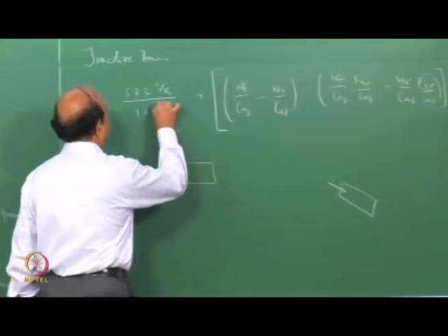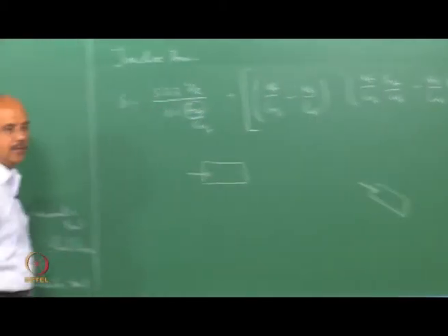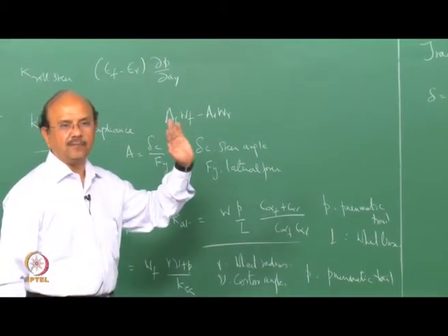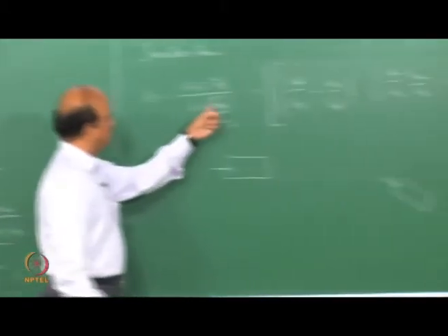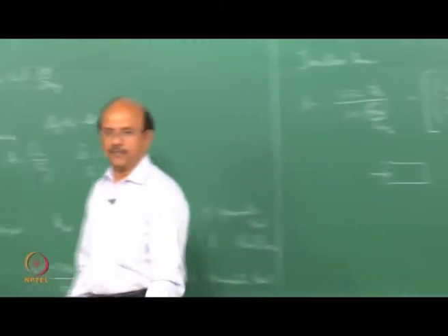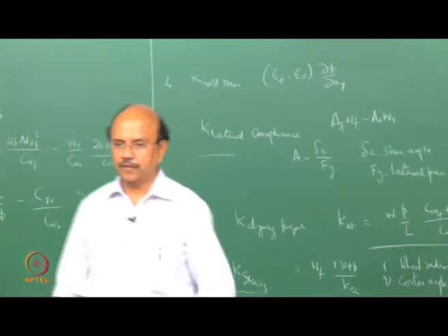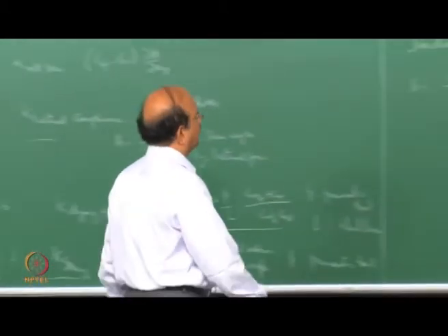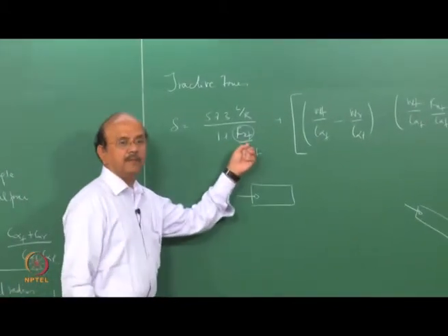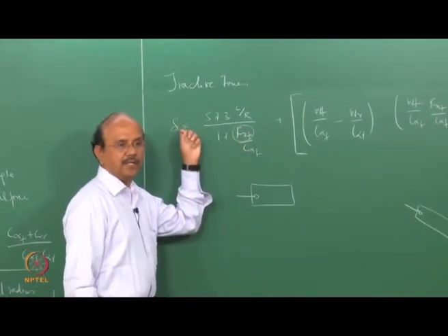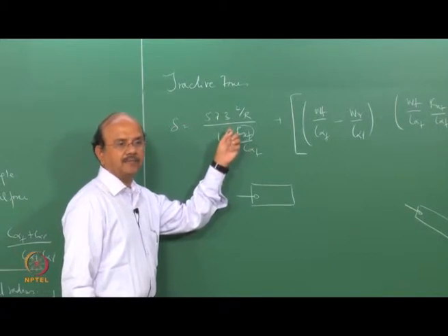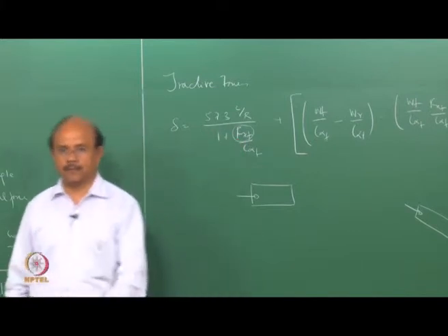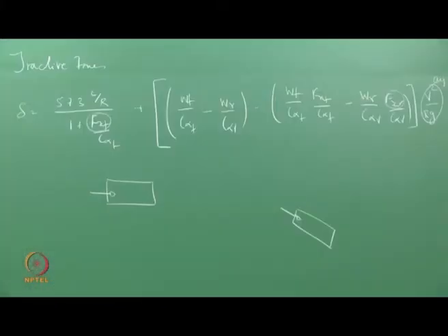Even for a neutral steer where the rest of the terms are not there, in other words, the first geometric term is affected by the traction. The very first term is affected by the traction. So what happens? The higher this term is, the lower delta is, and hence there's a tendency to oversteer or understeer?